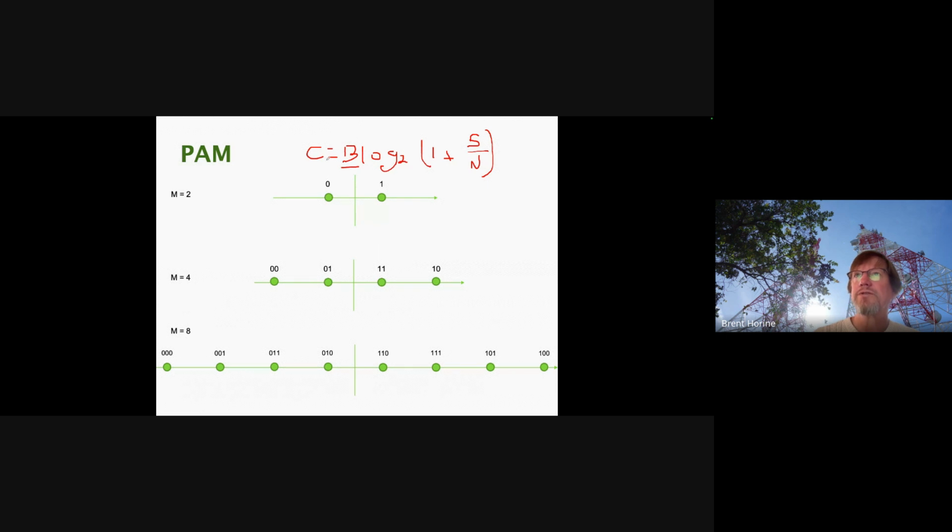How many symbols are you sending per second? But if we can send multiple bits per symbol, because we've got lots of signal power relative to the noise we might have, then we can go to a higher M and encode more bits per symbol for the same bandwidth and get a larger capacity, a larger data rate.